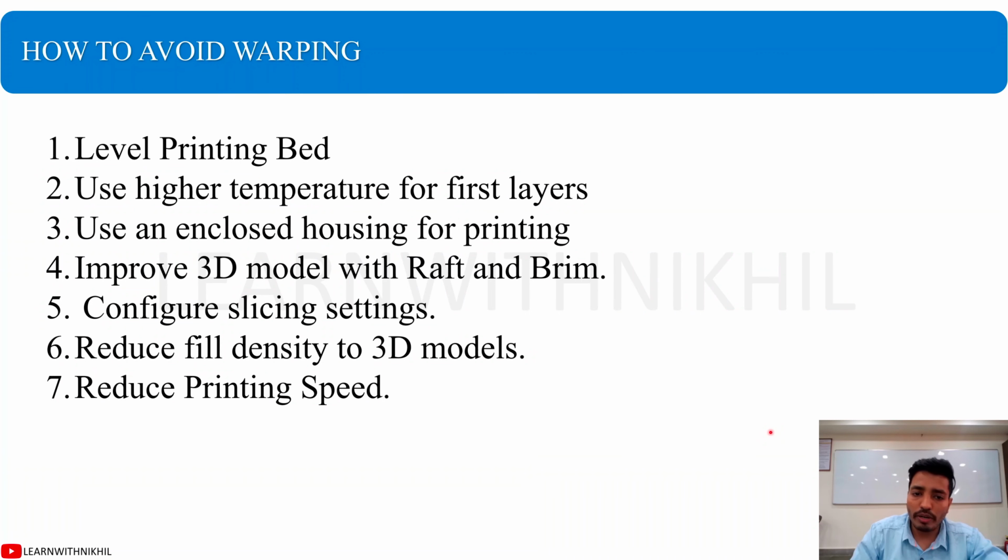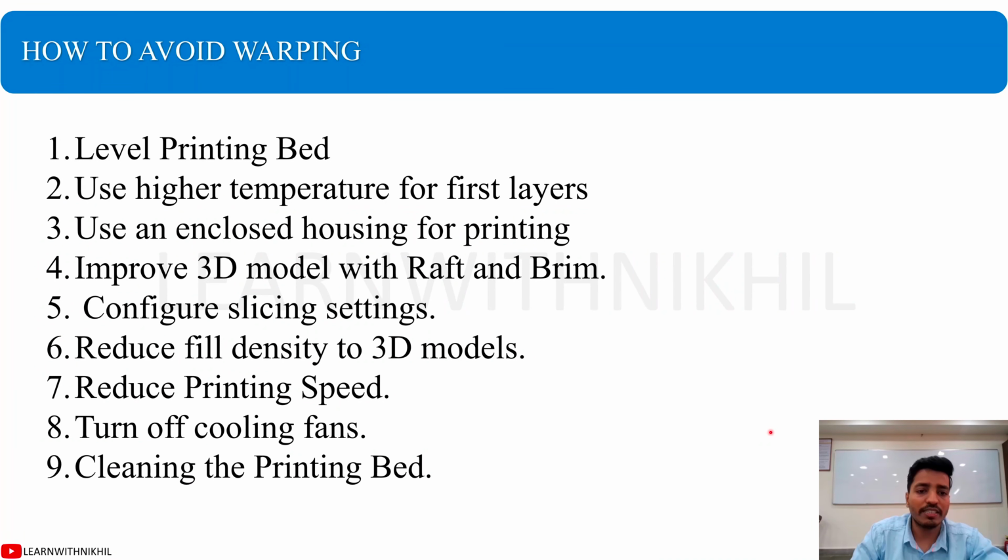You have to reduce the print speed, as I mentioned earlier. Cooling fans have to be turned off, or you have to maintain the proper percentage. Cleaning the printing bed is very important. As you know, there will be dust on the printing bed, and if there is more dust, the adhesion will not be proper. So your first layer will not stick to the build plate. So you have to clean the build plate properly.